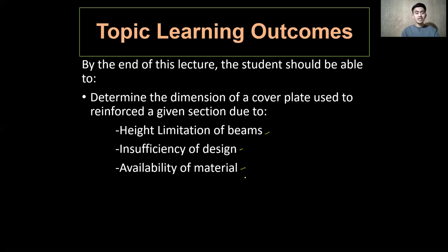You can purchase a material having a similar property to the original material that you are going to buy, and then you are going to supplement now that material by attaching some cover plates at the top or bottom of its flange. So those are some of the basic uses now of cover plates.